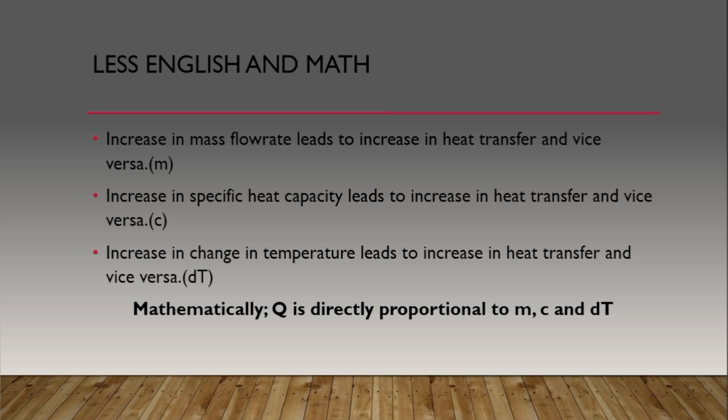So instead of you having a very, very high temperature for your hot stream, just to be able to transfer enough heat energy to the cold stream, you might just want to temper a little bit with your mass flow rate to make things balance up. It goes a very long way too, because it's also directly proportional to your heat transfer.